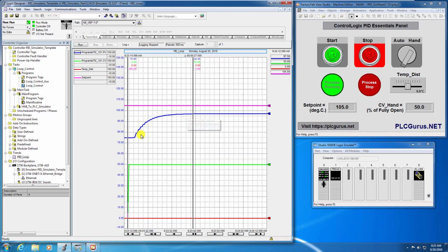Okay, so a typical first order response really mimics the charging of a capacitor, if you've ever seen the charging and discharging of a capacitor. So you can see 27.5, but we're a little bit high there at 99. So we are around 25 seconds. So this makes perfect sense. We entered a lag value of 5 seconds, which gets us to 63.2% around there. And then the final value, 5 tau or 5 lags, would be 25 seconds. So right about there. Perfect.